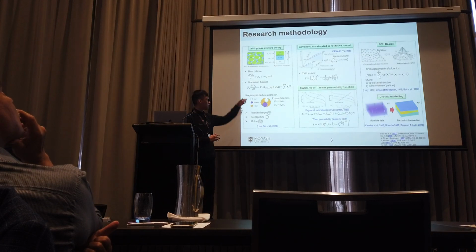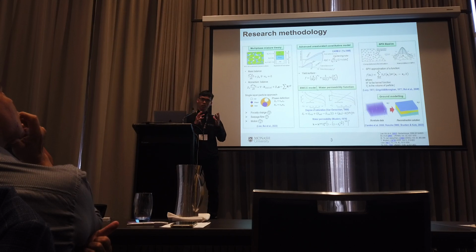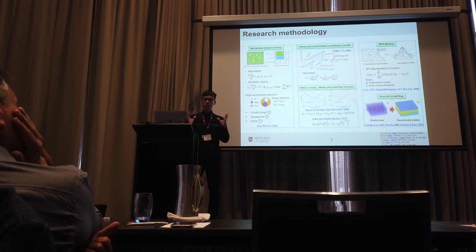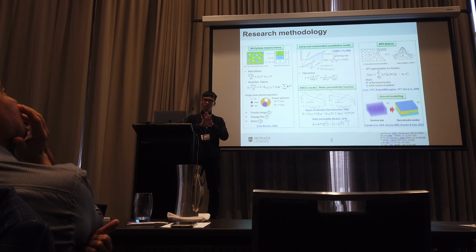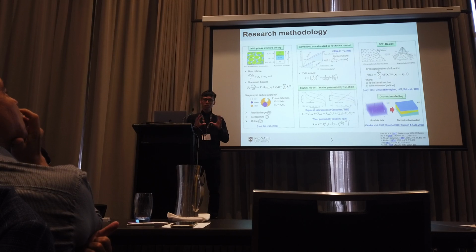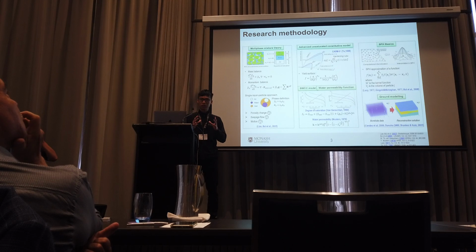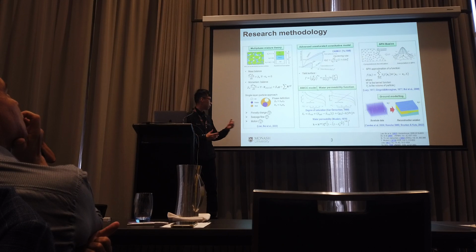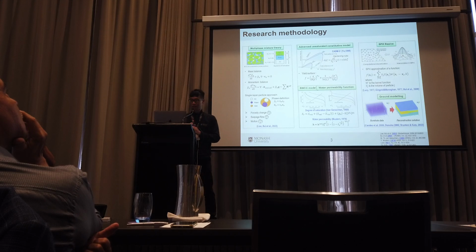First, we start from considering an RVE of unsaturated porous medium, including solid, water, and air, and then we apply the multi-phase mixture theory to establish the governing equation for each homogenized phase. And then after that, we use the single layer approach to combine all governing equations to establish a unique governing equation for the entire system, including porosity, suction change, solid flow, and the motion equation.